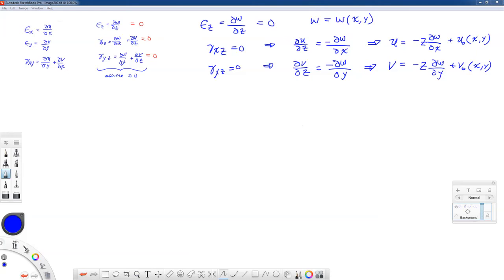Okay, now we do have some restrictions that are set forth that we're going to use. I'm going to read some of these out of Ugural's book. The deflection of the midsurface is small compared with the thickness of the plate. The slope of the deflected surface is therefore very small, and the square of the slope is a negligible quantity in comparison with unity. The midplane remains unstrained subsequent to bending. Plane sections initially normal to the midsurface remain plane and normal to the surface after bending. We're going to have gamma xz and gamma yz negligible, which is the assumption that we made right here.